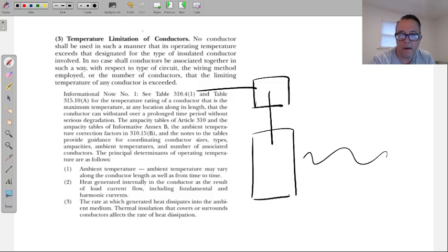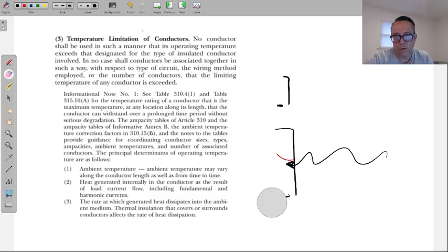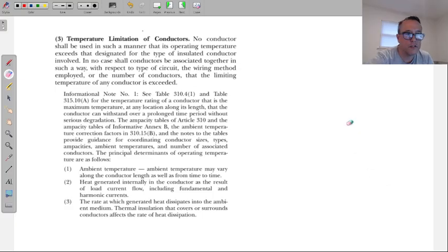As the crazy harmonics are produced from the branch circuits, before that current gets back over to the main panel, it gets run through a filter and then it cleans up the sine wave. I've only worked with it once. It was in a computer room for a television station, and I installed a couple of them. Nothing fancy, you just bring 3 wires to one point, 3 wires to another, and it works basically like a transformer when you get into wiring those up. So nothing crazy, but I did want to explain harmonic current because it is there, in case there was a curiosity.